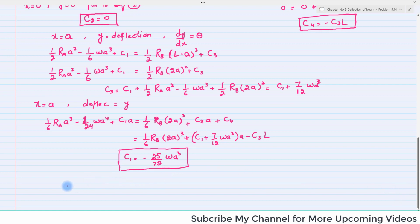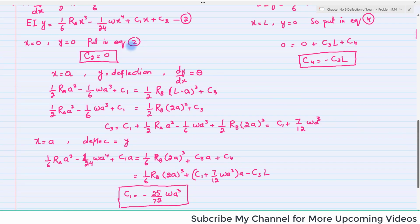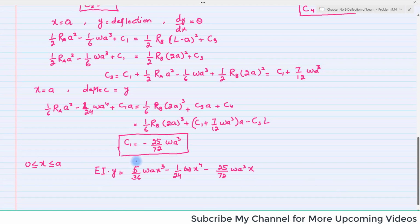So what we will do is use, for x greater than or equal to 0 and less than or equal to a, the equation of deflection: EI y equals 5 over 36 W A x cubed minus 1 over 24 W x to the power 4 minus 25 over 72 W A cubed x. Here you can put the value of R A, C1 and C2. So when you put it, you will get this equation.